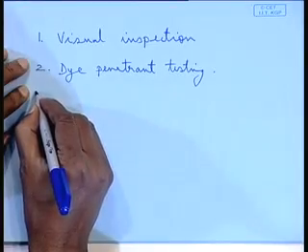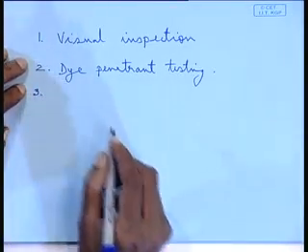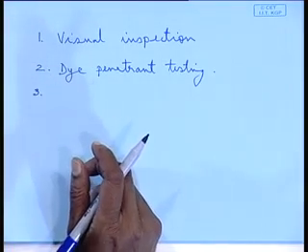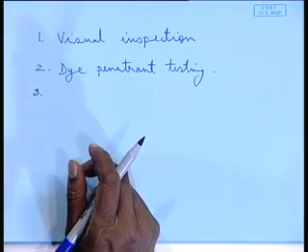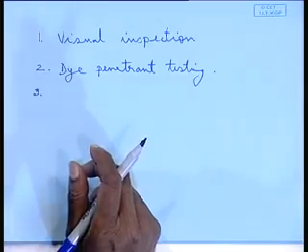The primary drawback, the limitation, is that it can only say either it is a surface crack or it is a through and through crack. If it is halfway between, how much, it cannot say, because if you have to repair the crack, then you should know how much it has gone in, right. Also, another drawback, the same as for visual inspection, is no record. Automatic records are not generated. You will have to later prepare a record that there was a crack, that was the defect, etc., right. That is also a limitation.